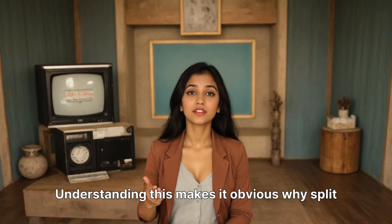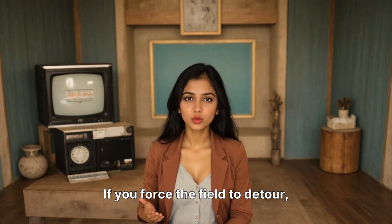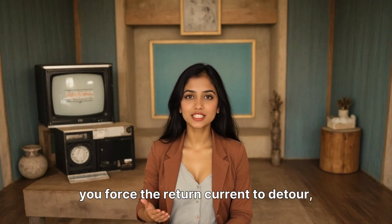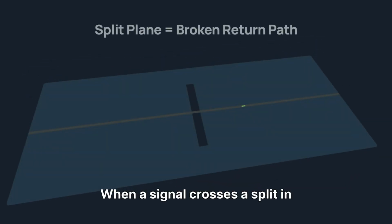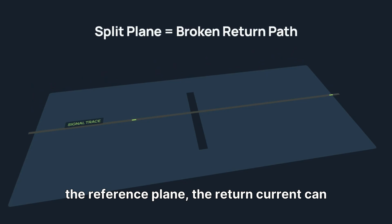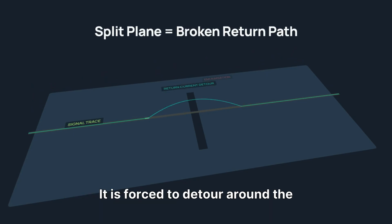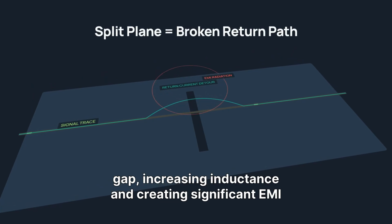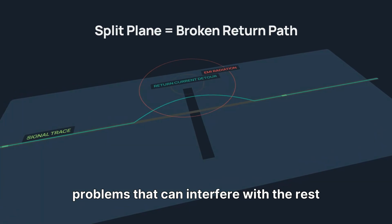Understanding this makes it obvious why split ground planes are so dangerous. If you force the field to detour, you force the return current to detour, and that's when your signal integrity begins to fail. When a signal crosses a split in the reference plane, the return current can no longer follow directly beneath the trace. It is forced to detour around the gap, increasing inductance and creating significant EMI problems that can interfere with the rest of your board.